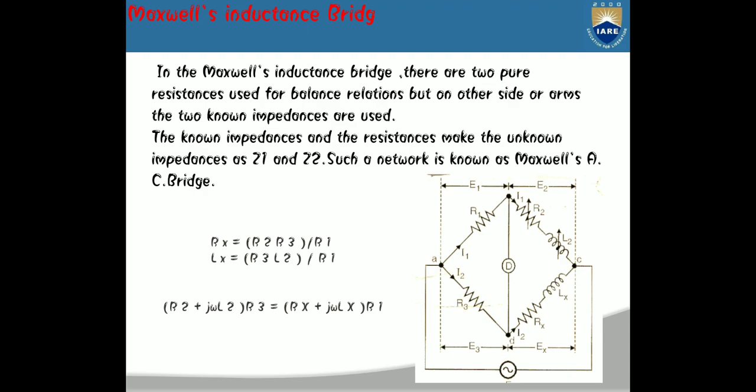Before those limits are approached, the ESR of the capacitor will likely have a significant effect and has to be explicitly modeled. Now, for ferromagnetic core inductors, there are additional constraints.